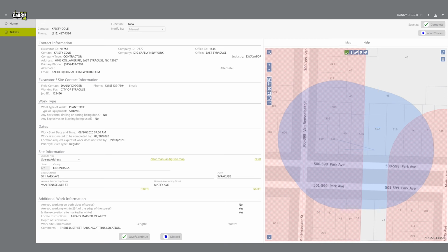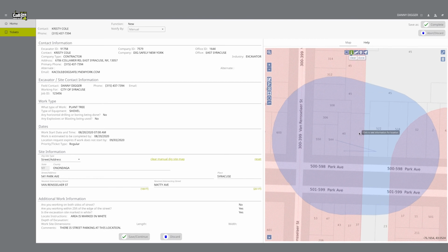The Show Map Information tool is very similar to the Show Map Features tool, except you must click on a location on the map. Clicking on the Show Map Information tool and clicking on the map will show the following information: city, place, parcel, and county. It will not disappear from your map until you click the X in the pop-up window or the clear text under the button. Clicking the Done text under the button will keep the information pop up on your map. When you're done utilizing this tool, click the button again. When it is in use, the button will be green. When the tool is not in use, the button will be blue.